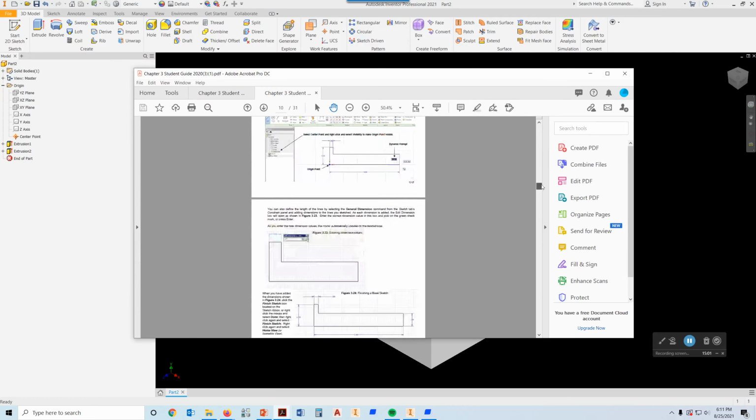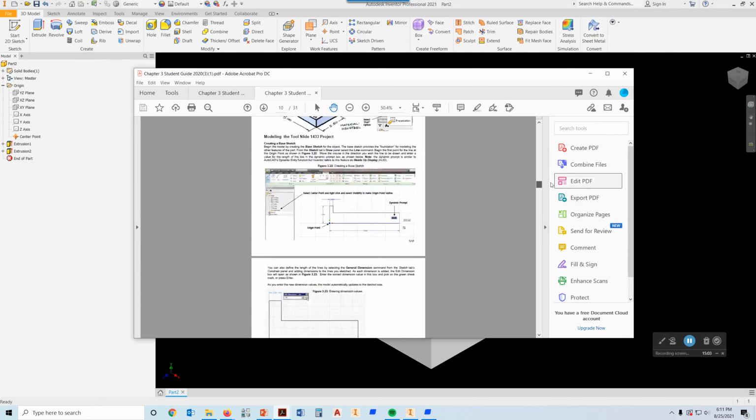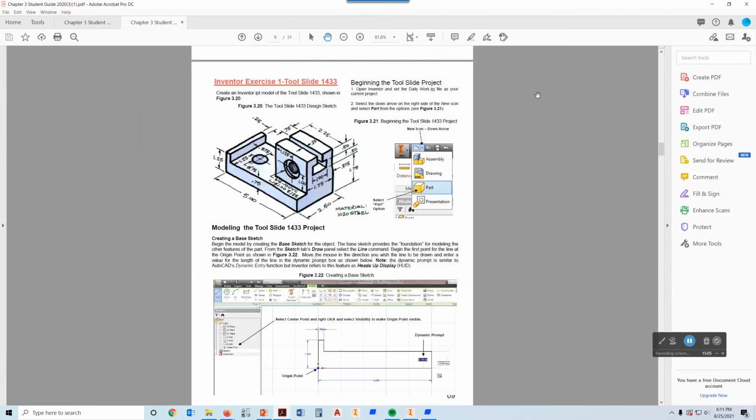And go back up to here. Sorry, expand on that. Okay, so look right in here. We have a slot that's 1 inch wide and it's 1/2 inch tall right there. And it's located 0.375 inches from this right side over here. And then there's another slot right in the middle of that that's 0.25 tall and is located 0.75 over, okay?